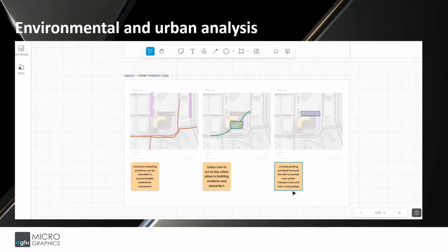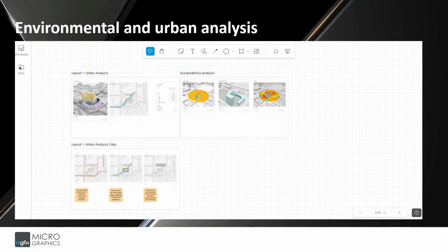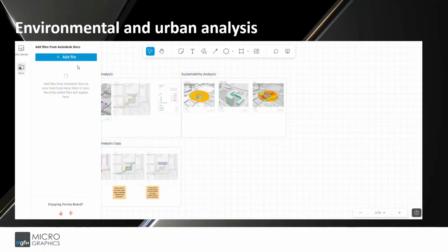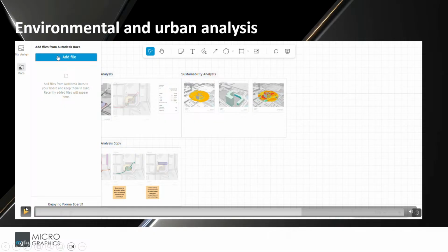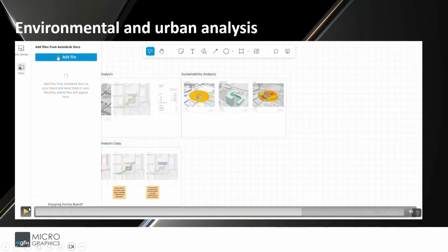And then also I've perhaps added parking there, but because my ArcGIS layers gave me insight to the bus routes, I could then understand that I do not need to provide as much parking for that area because I've got public transport. So not as many, let's say, workers or pedestrians will be traveling by their personal cars, but they might be traveling with public transport, be it the bus, the train, or the taxi, which is quite common. So, okay, let's go on then.